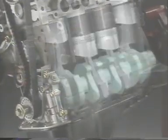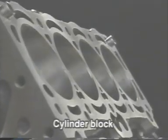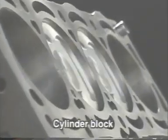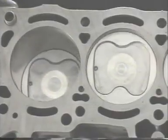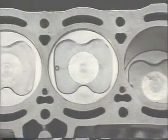The cylinder block constitutes the framework of an engine. Together with the pistons, the cylinder block plays the important role of maintaining compression pressure and bearing combustion pressure. The inside of each cylinder is finished to high precision by honing to minimize wear of parts and prevent gas leakage.